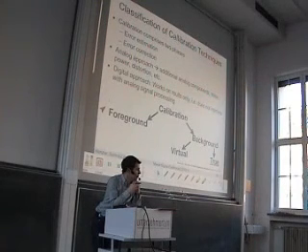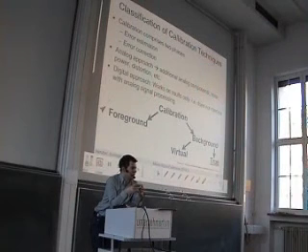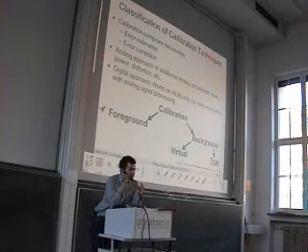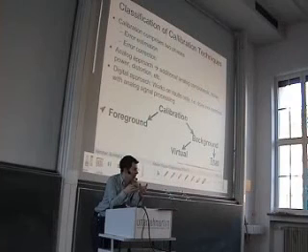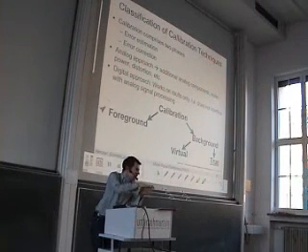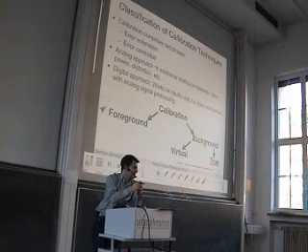Well, this is easy, sure, but it requires that you have this startup phase, this correction phase at the beginning. And if the error develops over the operation period, for instance, because the voltages change or the temperature changes or whatever, then you have no chance to react to these additional errors, because you have done the calibration at the beginning, and from this point on, you run the system.